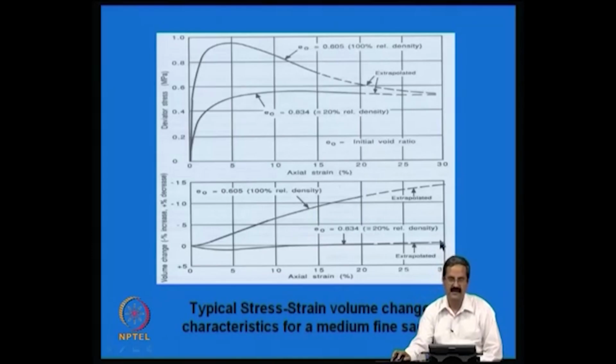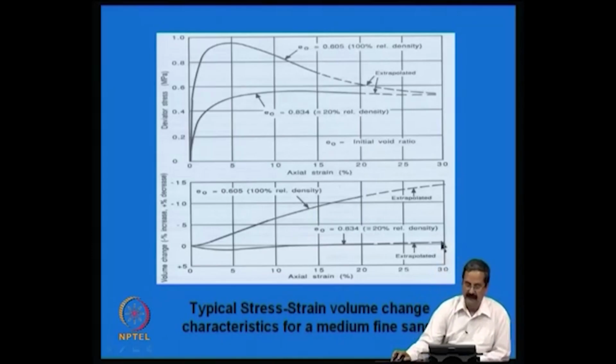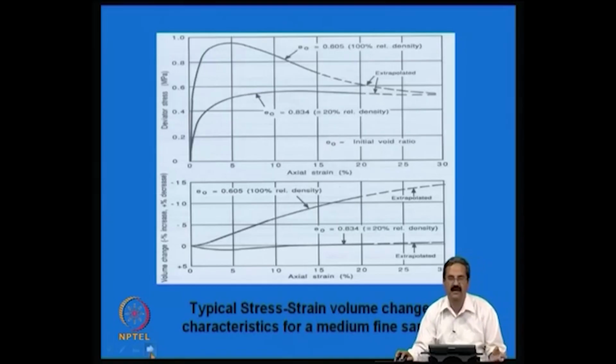So, what is important is that compaction is a very important variable, and it has a significant influence on engineering performance, whether it is shear strength, compressibility, swell behavior, collapse behavior, stress strain response, or susceptibility to moisture changes. One needs to look at it very carefully and see that this is all implemented in actual practice in a proper way.